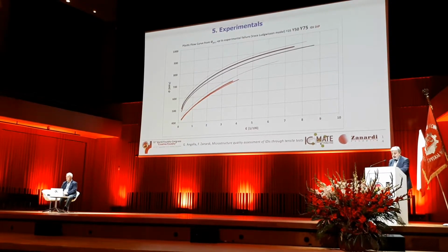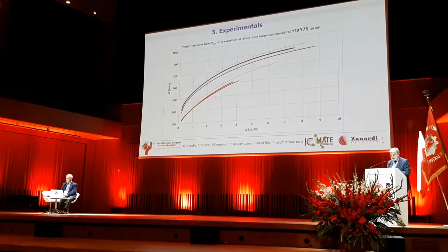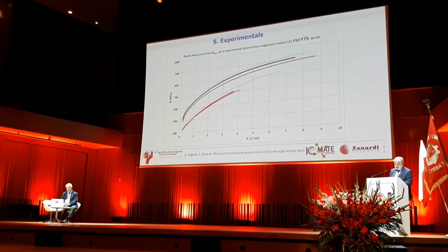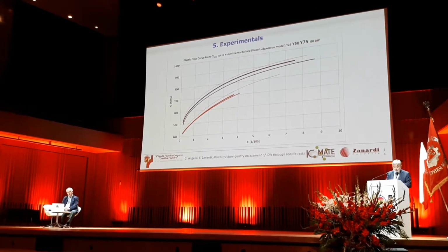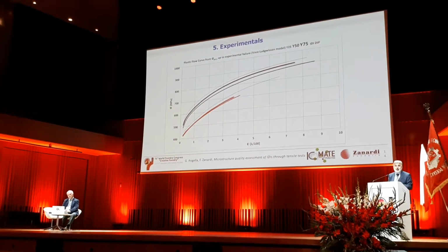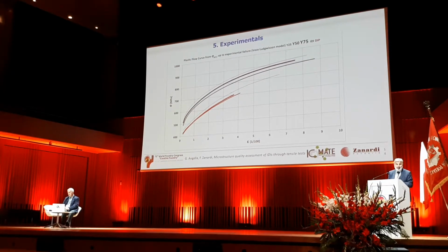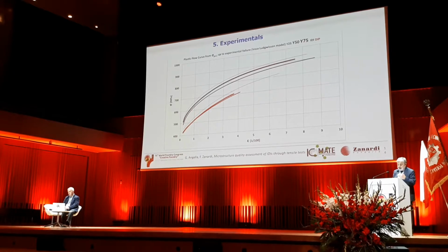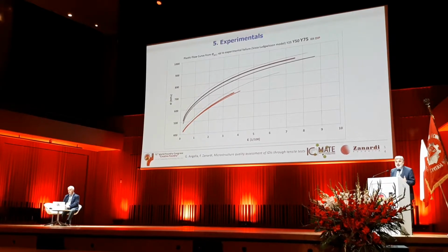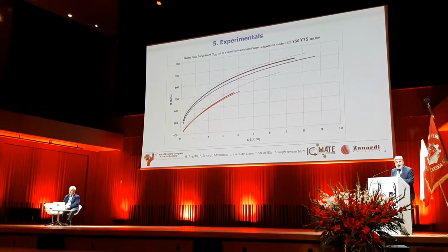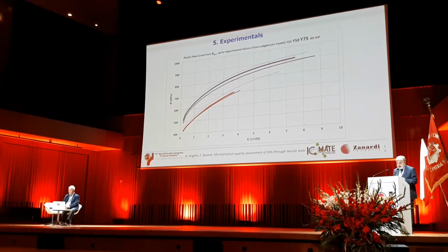So 75 is the thickest line, the 50 is the medium line, and the 25 is the thin line. In red, as usual, you see the conventional ferritic ductile iron as cast in the mold, while in black you see the IDI, the isothermed ductile iron.